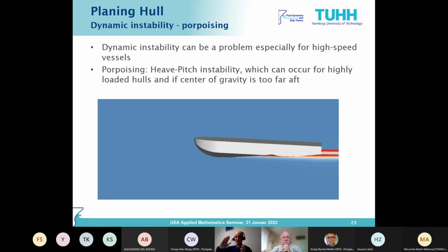When the ship hull is going in, but at the same time does a pitch motion going upwards, the velocity with which the cross section is entering is reduced due to the ship motion, but it does not necessarily mean that in this two-dimensional frame it is exiting. But it can be the case.